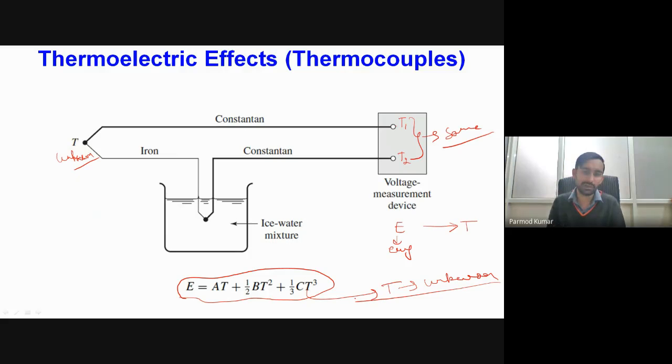While calibrating our thermocouple for the first time, at the time of calibration we have to maintain the temperature at a known value, measure the output voltage, and then develop a relationship between the output voltage and the known temperature field. Once our instrument is calibrated, then while using it, by just knowing the value of the EMF, we will be able to relate it to the corresponding temperature.